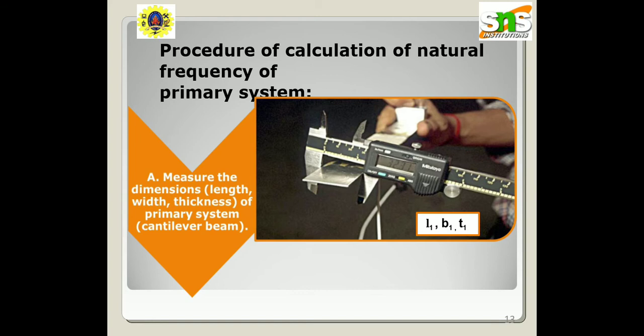Given a motor with a mass M1 attached via motor mounts to the ground, the motor vibrates as it operates, and the soft motor mounts act as a parallel spring damper, K1 and C1. The graph shows the effect of a tuned mass damper on a simple spring mass damper system excited by a vibration with an amplitude of one unit of force applied to the main mass.